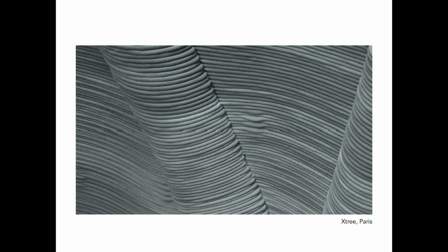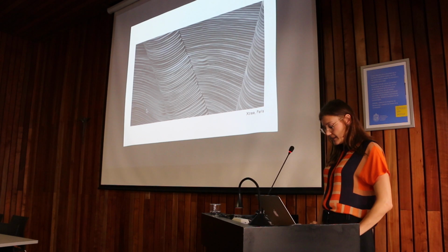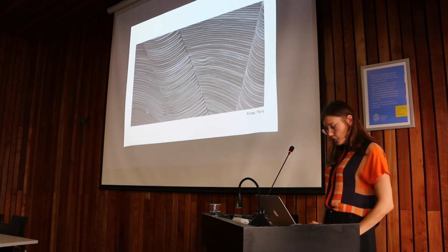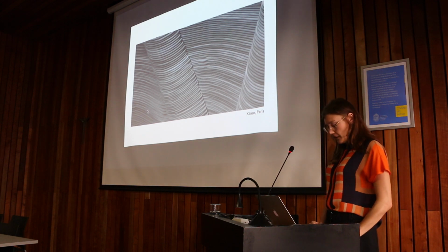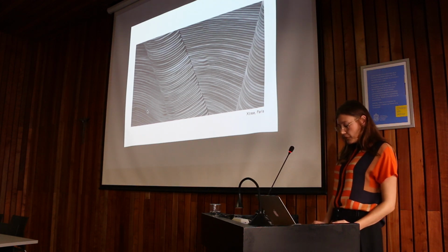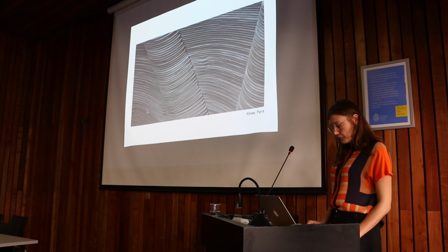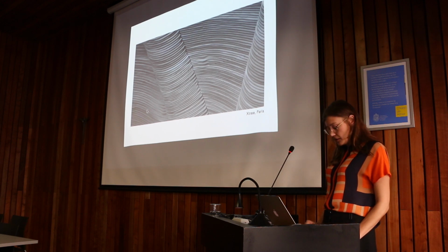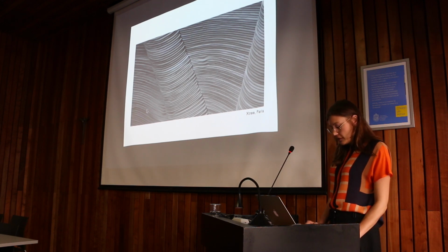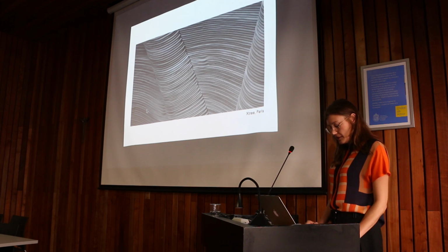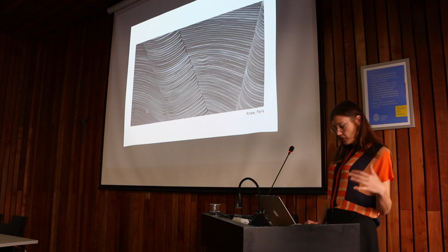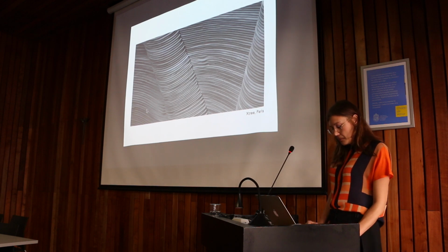The process of 3D printing signifies a fundamental departure from conventional casting techniques, in that the materialization of concrete flow is no longer controlled by the opposing force of a predefined formwork, but by the self-supporting capacity of the material itself, coupled with the path of deposition. The process combines two main material operations, that of delivering material to the nozzle by pumping the concrete, and that of placing it by deposition.